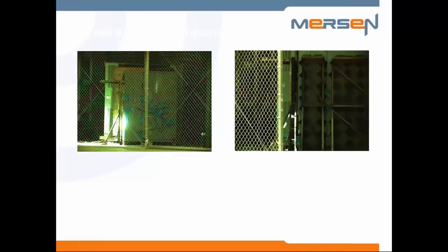And now if we look at these side by side, the test on the left was the original test number 9 that had no high-speed switch in it, and it goes on for 450 milliseconds. The one on the right will be the high-speed grounding switch protection. So these slides are the first frames in the high-speed videos where arc light was detected. So this would be the beginning of the arc at point B in the previous trace.